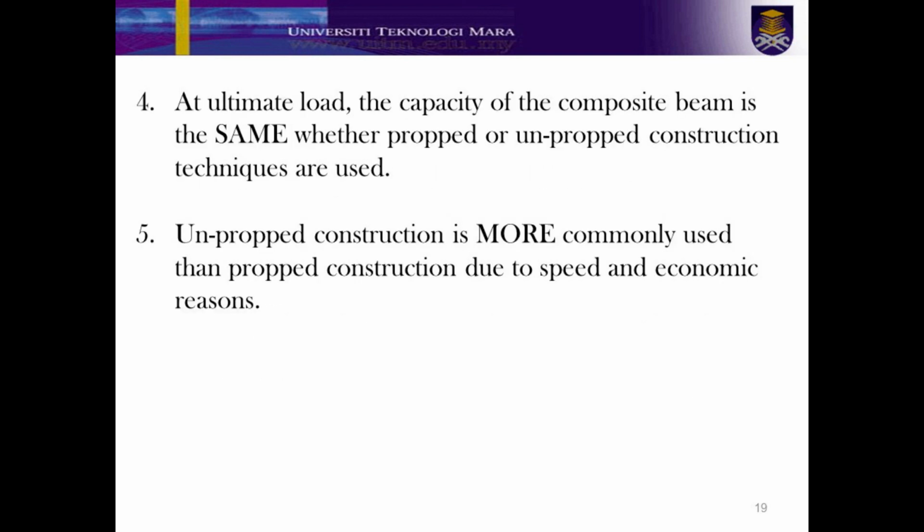At ultimate load, the capacity of the composite beam is the same whether propped or un-propped construction techniques are used. Un-propped construction is more commonly used than propped construction due to speed and economic reasons.